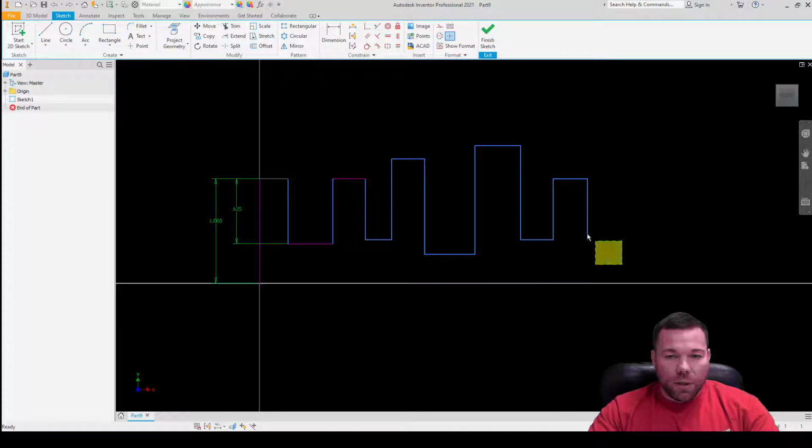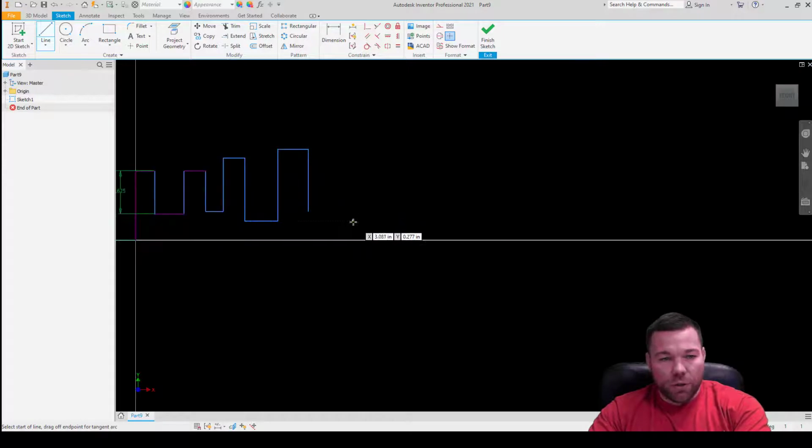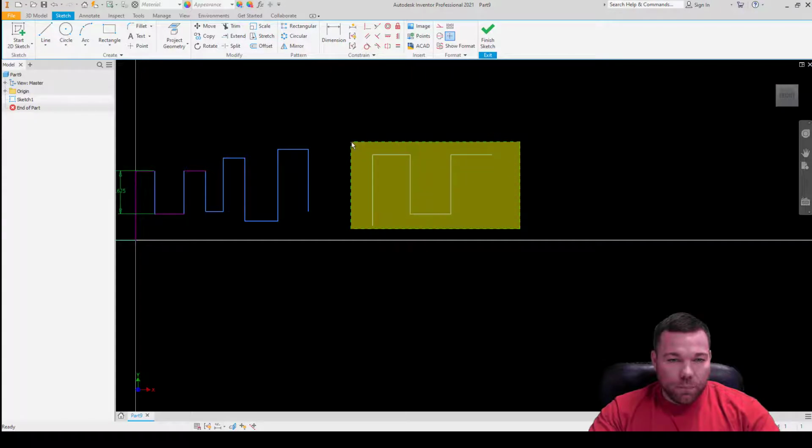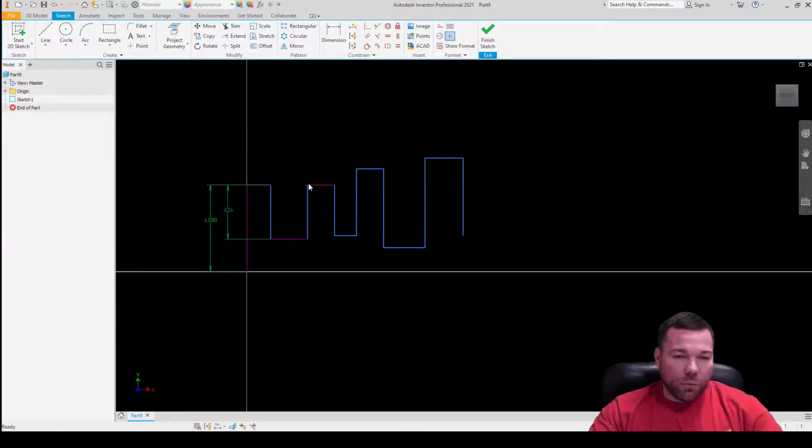But when I was actually drawing this part, let me draw a new one. I think it's because I'm finished that command. So if I were to draw a new one, and if I come up, see that solid line is created now. I have a tracking line, and then I have that solid line. That is creating the collinear constraint automatically. So those are automatically collinear now. So that's basically how this one already got collinear to this one.